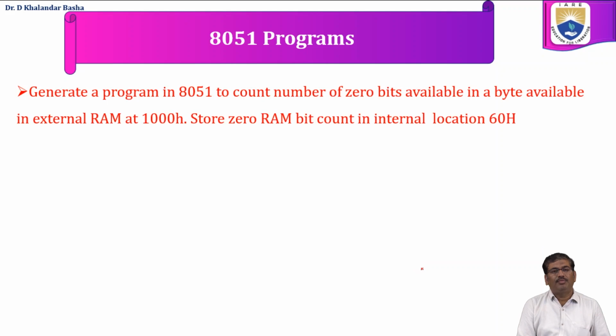Next, generate a program in 8051 to count the number of 0 bits available in a byte in the external memory at 1000H. Store the result in RAM bit count in the internal location 60H. So we are going to take data which is of 8 bits. Here the objective is we need to find how many zeros exist in this data.